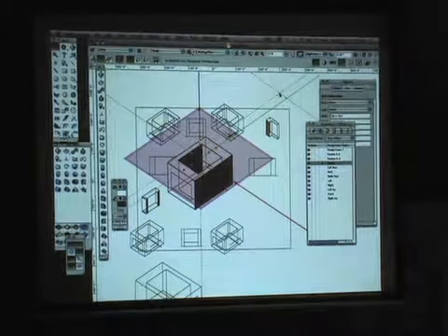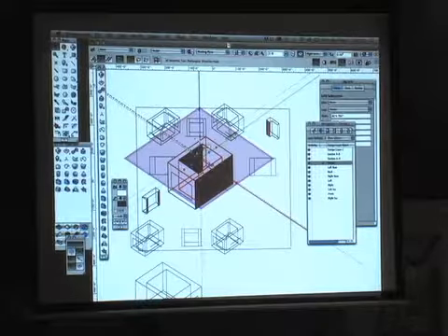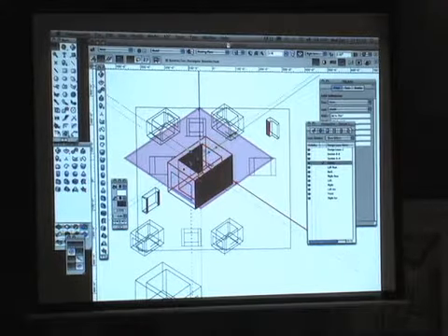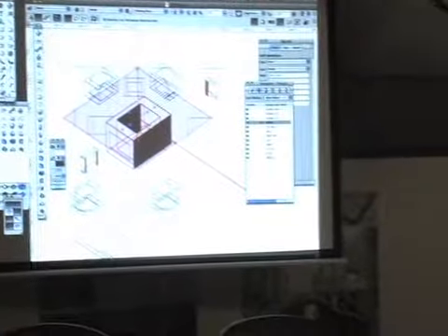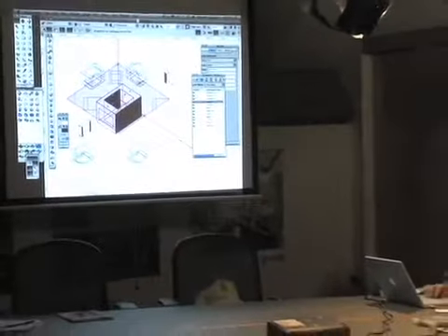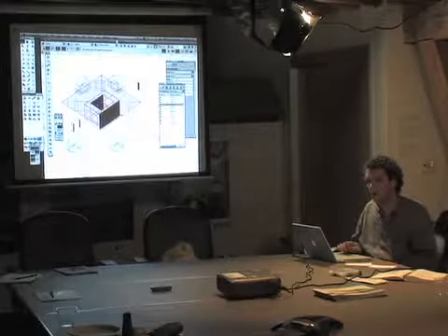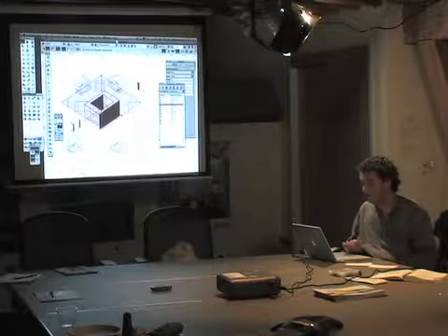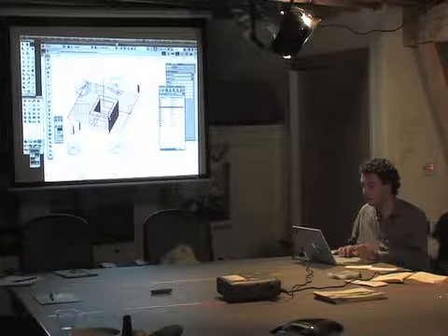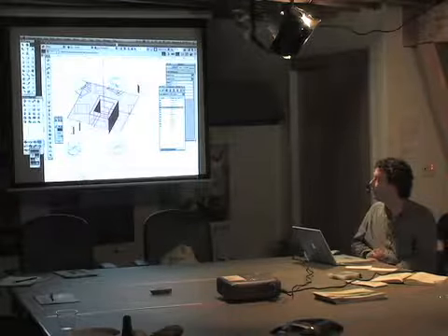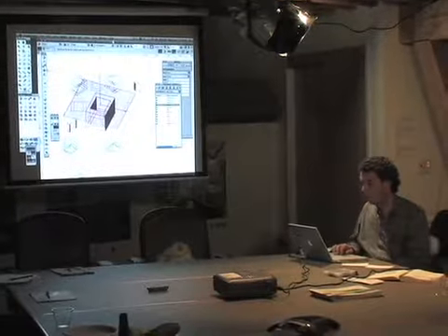The thing I found with the design layer viewports is as your model grows, your orientation sort of changes and things begin to overlap. I'm working on this in 8th scale, I think, and I made these viewports at 16th. So you can have different scales on different layers, like we always have been able to. I think design layer viewports can be a pretty neat tool for modeling. It's easy enough to flip around now and work on it, but you're able to see it here from a couple of different angles, which you have been able to do in AutoCAD before.